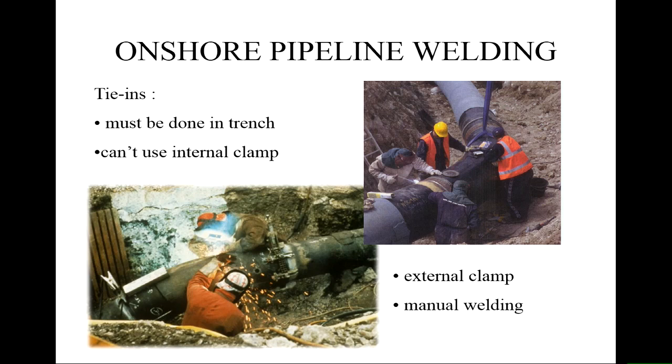Sometimes you can do vertical down, but sometimes you have to do vertical up because the spacing between the parts can't be controlled as well. And that's always a problem with fittings. You can't always support them and clamp them as well as you would like. But you don't usually have productivity limits. You can spend longer lining them up and doing everything by hand. So what's good in these cases is that you have the time and the effort and the expertise to line things up properly.